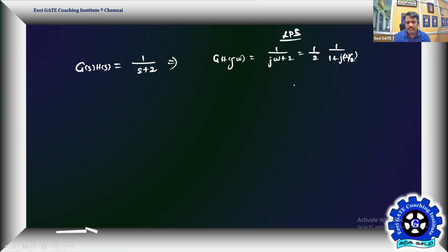So then the frequency response will be like this. The gain will begin with 1/2, and in the asymptotic Bode magnitude plot, the cutoff frequency is the pole frequency, that is at 2 radian per second. That's how we get bandwidth, meaning up to 2 radian per second. That's your omega b, we can say that's the bandwidth frequency. So 0 to 2 radian per second is your bandwidth for this low pass system.